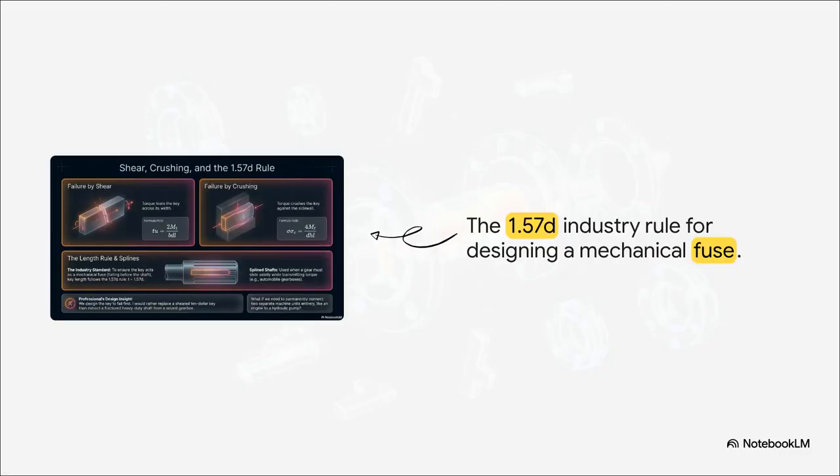And to protect our massive complex assemblies, we use a brilliantly derived industry standard, the 1.57D length rule. By setting the key length to exactly 1.57 times the shaft diameter, we mathematically balance the shear and crushing forces. We are deliberately designing the key as a mechanical fuse. Under a catastrophic torque load, we practically guarantee that the $10 key will fail by shear long before we ever have to extract a fractured, heavy-duty shaft from a seized gearbox.